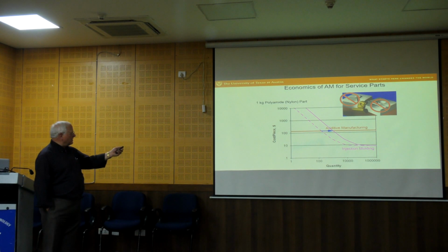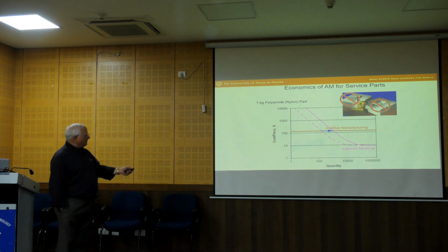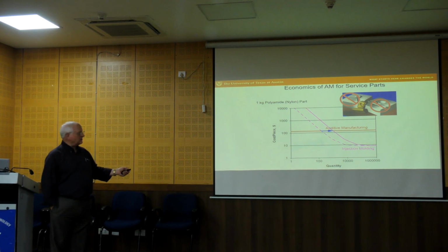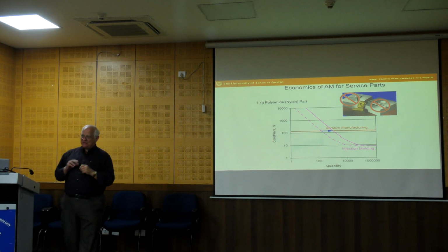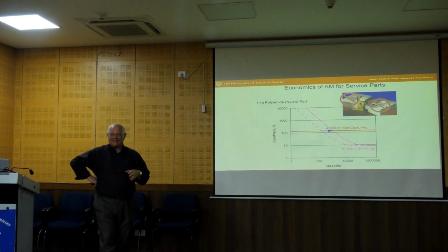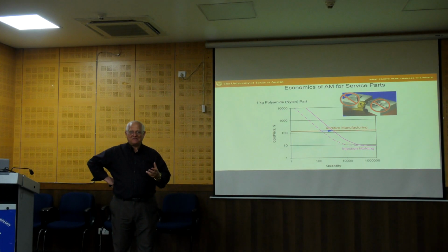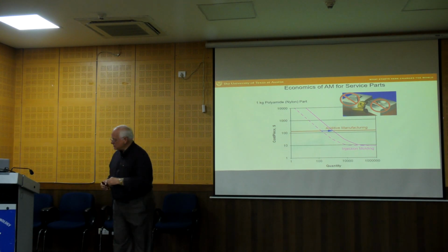So if I have this schematic scenario, if I increase my tool cost up here, let's say in this case from $10,000 to maybe $12,000 or $13,000 or $15,000, this curve changes, and I move my break-even point maybe out to 200 or 300 parts. And so this brings in the second of the criteria for making a part economically feasible: I want it to have a complicated geometry. So low production runs and complicated geometries.